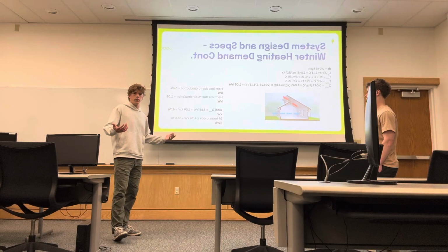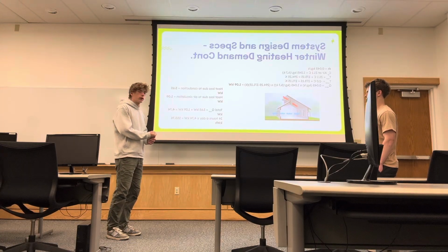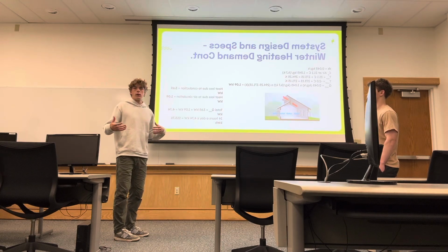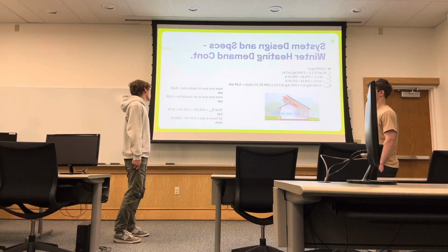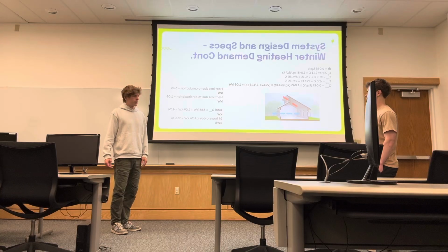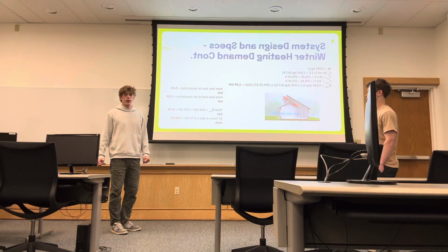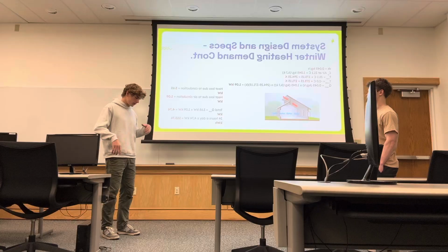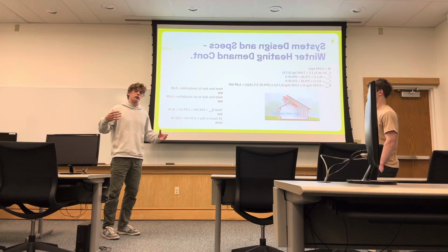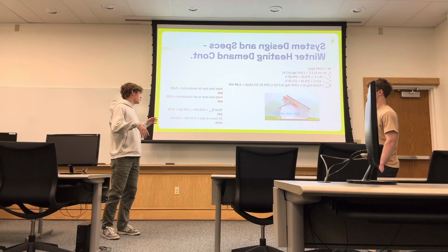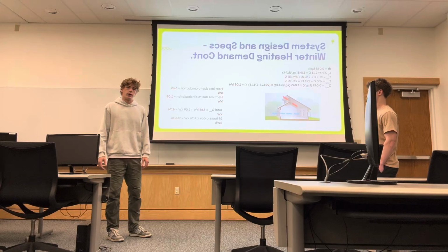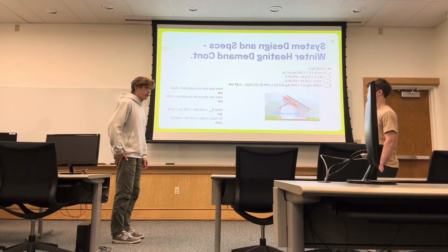Then we added the Q dot of the conduction and the Q dot of the ventilation to find the total loss of heat energy in the system, which we determined to be 4.74 kilowatts. We know that we don't want the internal energy of the system to change, so Q in is equal to Q out, and the amount of energy we need to input into the system is the same as the amount of energy that leaves it.